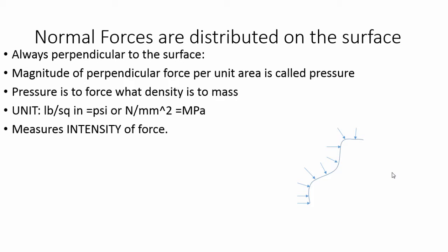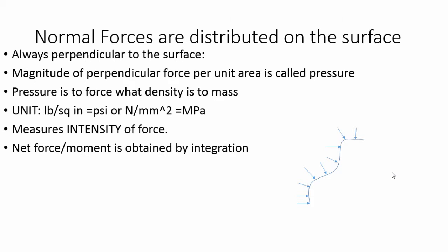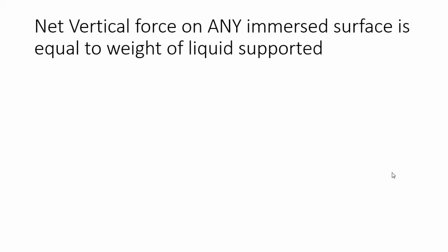What it measures is the intensity of the force, not the net force. If you want to calculate net force or net moment or something like that, you have to integrate. Okay, so please remember, units are important. What it means is force intensity. Pressure is to force what density is to mass. Very good. So we now know what is meant by normal forces, distributed normal force.